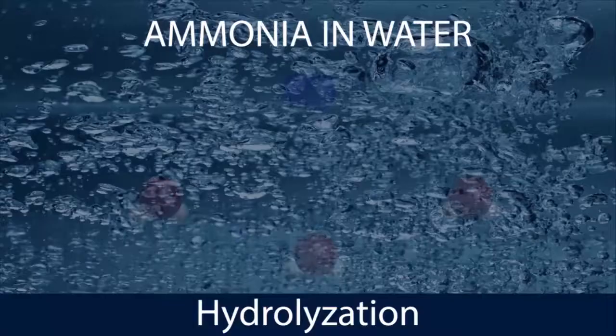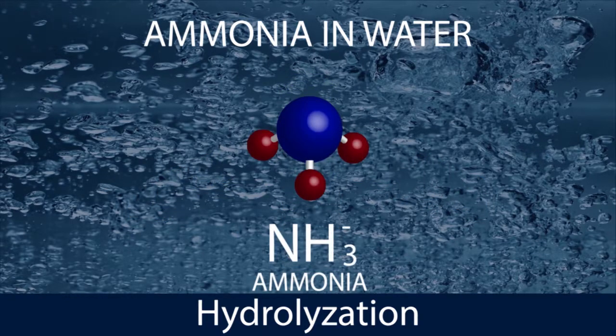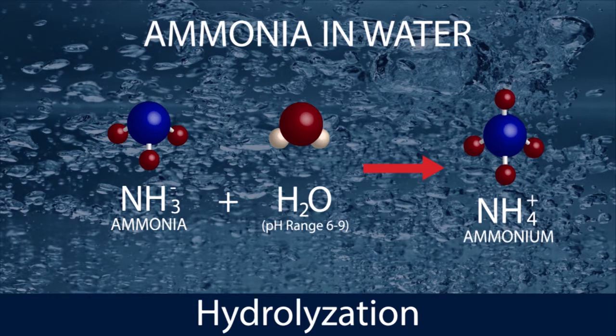As a natural reaction in an aqueous solution, or in water, the vast majority of organic nitrogen immediately hydrolyzes into ammonia. Due to the pH levels of typical wastewater, most of the ammonia then automatically converts to the ionic form ammonium. No bacteria is necessary for this conversion, it just happens.